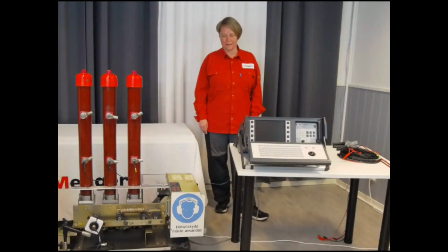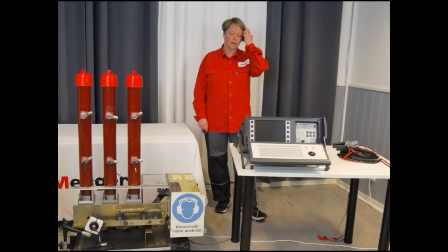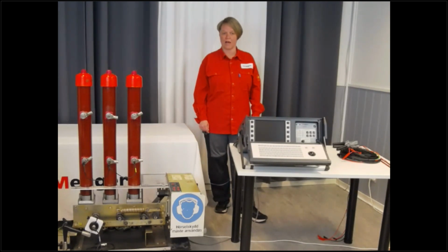Hi and welcome. My name is Boel Ekberg. I'm the application specialist of the circuit breaker in the factory of Megger in Sweden. I'm going to do 2 demos this afternoon. I'm going to start with a measurement with our small analyzer, Eagle, where I'm going to do a normal timing and also measure coil current and motion. In 1 hour, I'm going to continue with a measurement with TM800, where I'm going to do dual ground, with the circuit breaker grounded on both sides.